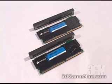Also keep in mind that a lower CAS is much better than a higher CAS. For example, a CAS of 2 will result in better memory performance than 2.5 or 3. So try and keep the CAS as low as possible when overclocking.